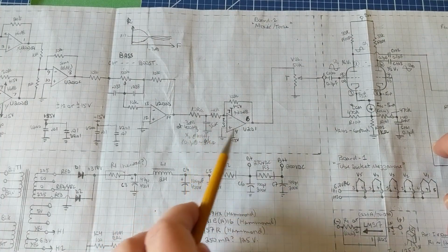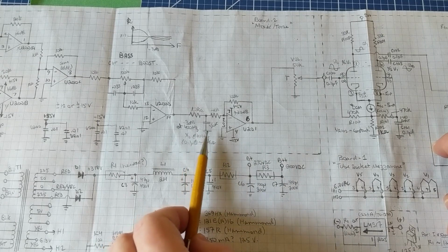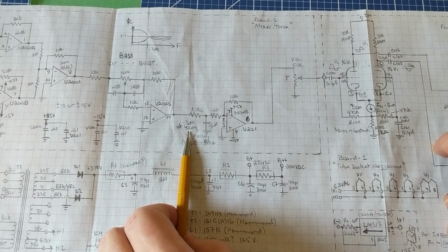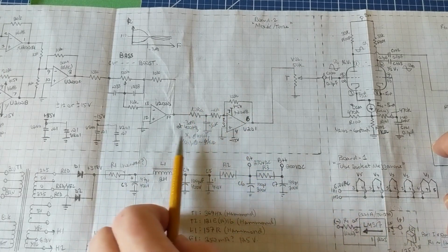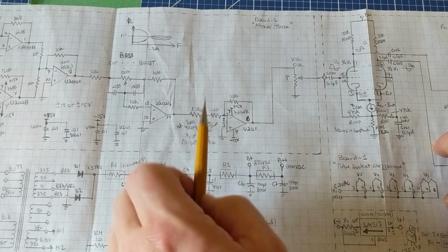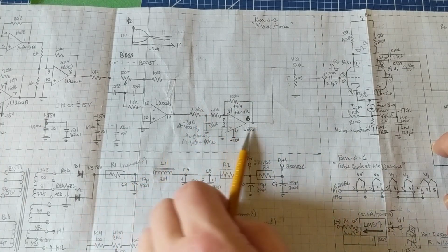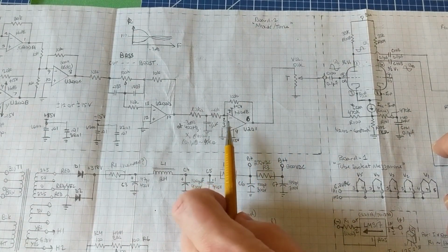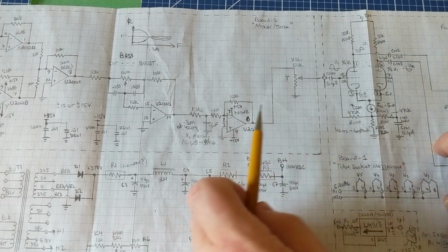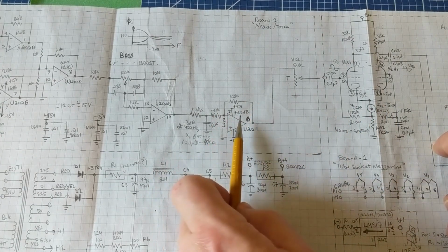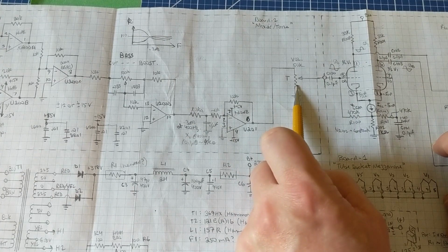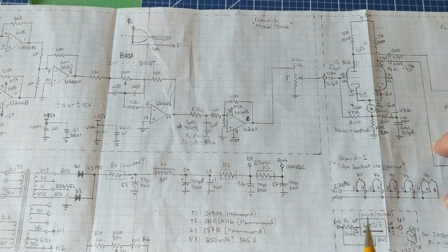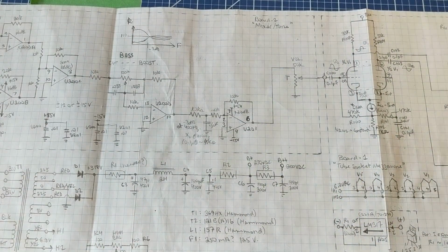This is the passive low pass filter. Initially I had it set to have a 3 dB cutoff point at around 400 Hertz. I'll probably mess around with that a little bit to fine tune it. I can change the capacitor up and down to change the crossover point. The final op amp is the buffer going to the phase inverter, and it just provides a fixed gain, which I then use the trimmer to cut down such that it doesn't oversaturate the output stage when you're at full boost on a line input.